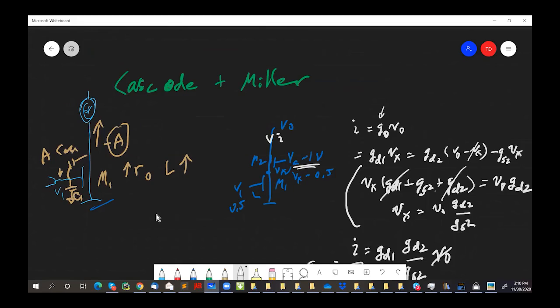And so you generally don't bother with it for the PFET that's sitting on the top here, because you can afford to make that PFET really, really long. And so you just put a long PFET up there and then two short wide NFETs down here that together make a high output resistance and a high transconductance. So if you make them wide and short, they can have a big W over L and you can get a big transconductance for the same current.